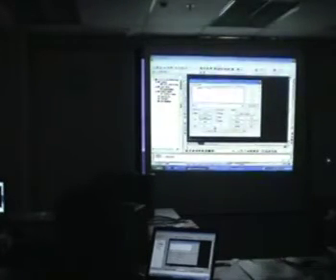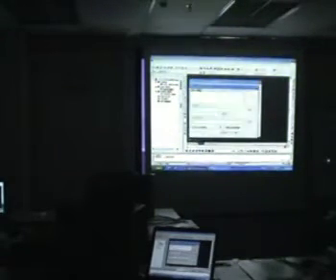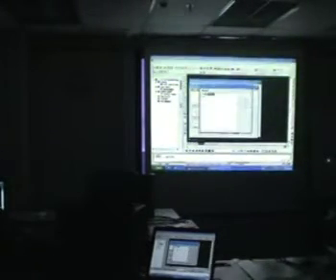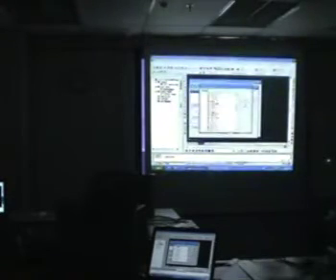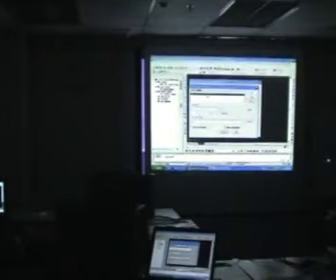And from this text, we're going to create an XYZ text file. I'm going to use report. I'm going to go to options. This is where we set our report template, meaning what's the first column, what's the second column, what's the third column. So I'm going to go to expression and extract x1. Add. So we've got our first column. Then I take the second one, that's y. So we've got x and y.